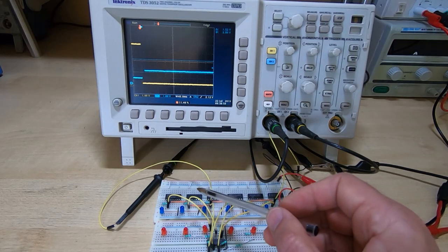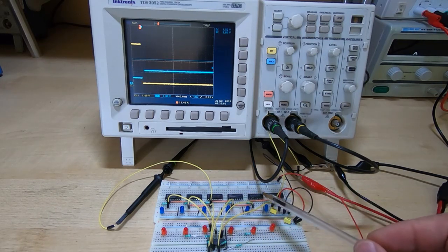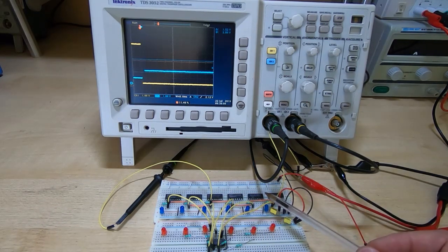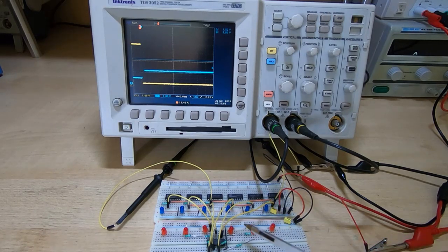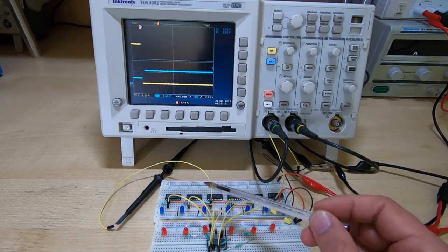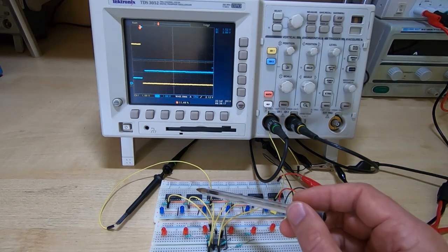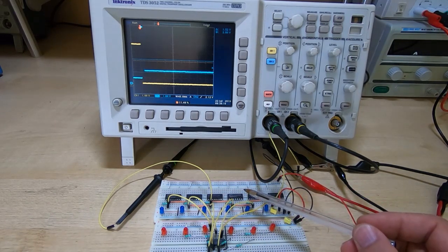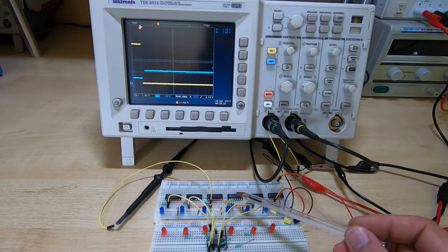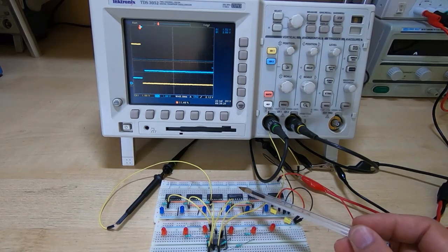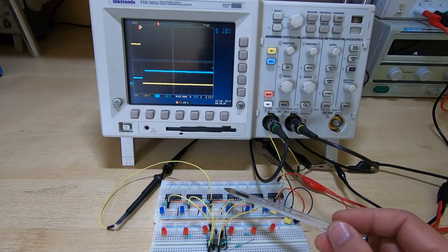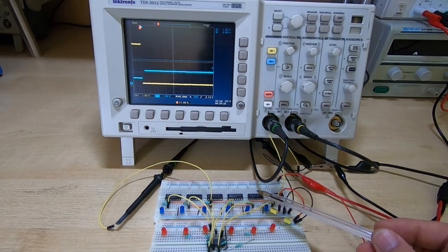The top breadboard has 6 ICs, all of which came out of the Altair that I showed in the previous videos. The bottom breadboard is just a simple 74LS04, and the way this is arranged is I have the top 6 chips all receiving a common square wave signal from a signal generator, so they should all be switching at the same rate and at the same time.